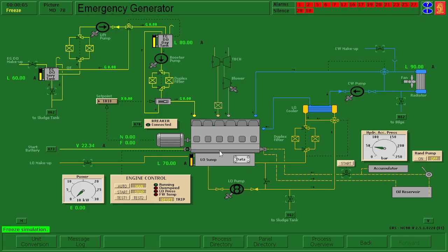So here our emergency generator is, as we can see, a diesel oil generator. We have the diesel oil generator makeup valve. Opening this valve will fill the emergency generator diesel oil service tank. This tank comes with a sludge tank valve, a tank drain valve, and this is because if you have the oil sit for a while, oil has a lot of water content in it. It's kind of crazy because oil's hydrophobic, but it's true. It's like